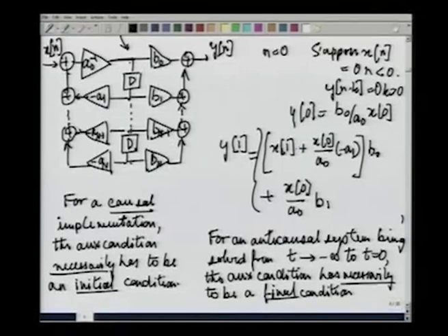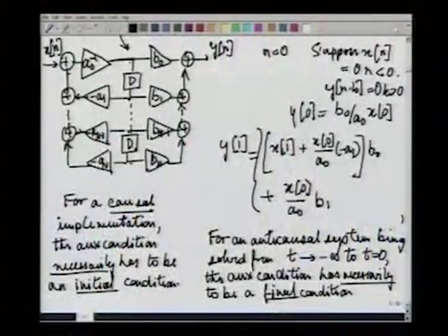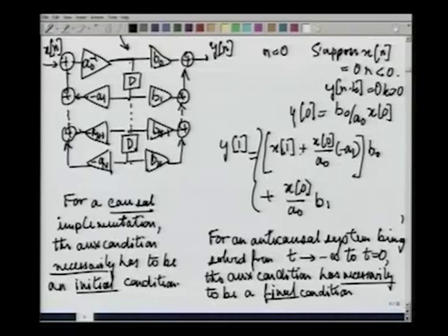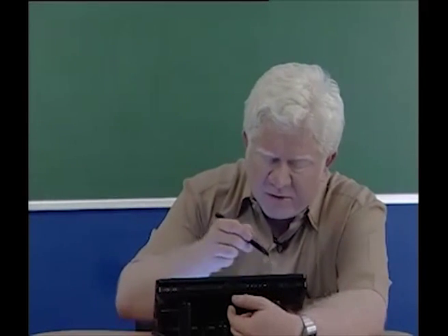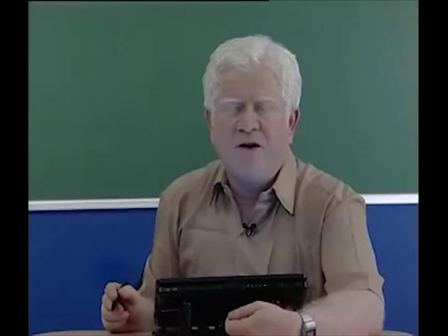It has incorporated the value of x 1, it has incorporated the delayed functions that have arisen in the meantime. Now clearly you can see y 1 uses both x 1 and x 0. Y 2 will use x 1, x 0 and x 2 and so on. So after n instants, where n is the order of the system, the past n values of x will come into the picture, and even older values will come into the picture because of the autoregressive nature of these blocks on the left side, and the system completely starts functioning as it is supposed to.